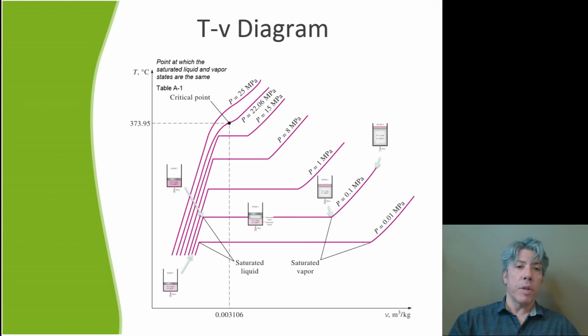So we'd get to a point where the temperature just increases continuously rather than going through a latent change. The change from liquid to vapor is instant. And that point is called the critical point, and the temperature and pressure there are called the critical temperature and critical pressure. You could even talk about the critical volume, though we usually don't.